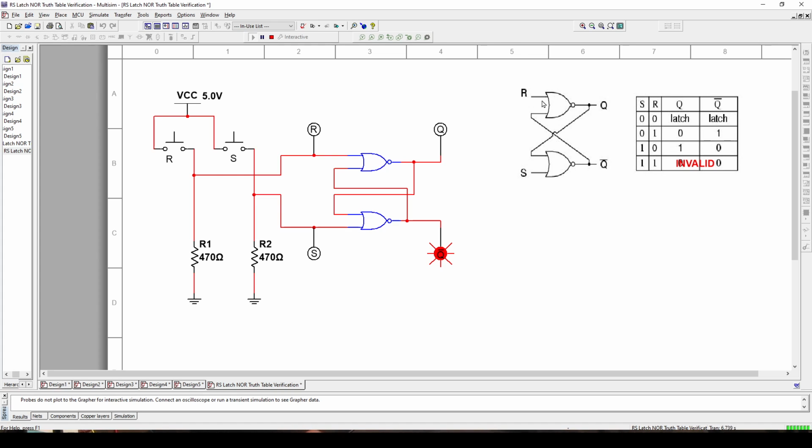Okay, so when you change that over here and nothing changes here, that gate is being triggered quicker, and then the condition changes and that one follows. And then if you trigger that one momentarily, then this gate is being triggered first, and that signal travels through the circuitry, and that gate is going to follow. So propagation delay actually makes it possible for this device to exist in real life.